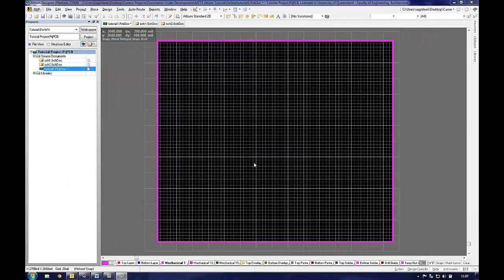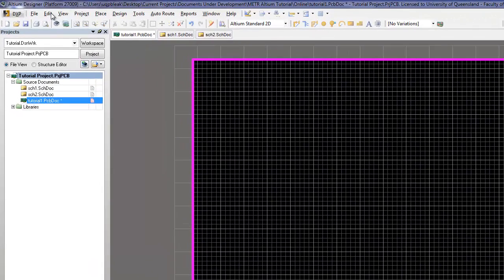The origin is a point of reference for any measurement related to the PCB. It often helps to set the origin to the bottom left-hand corner of the PCB so that distance calculations can be accurately measured, although moving the origin regularly throughout the design process may assist with component placement. Click on the menu bar, Edit, Origin, Set.